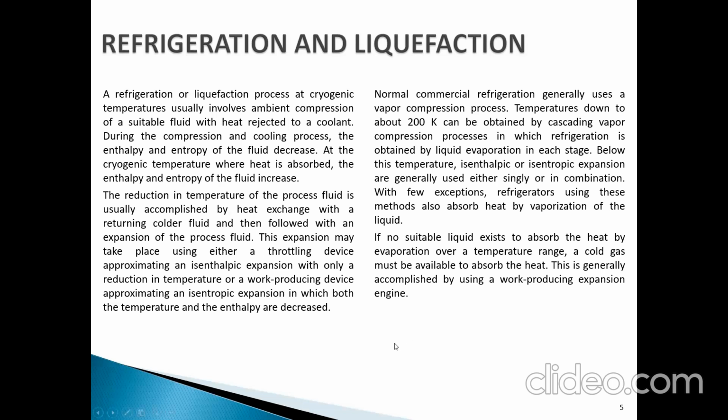If no suitable liquid exists to absorb the heat by evaporation over a temperature rise, a cold gas must be available to absorb the heat. So this is generally accomplished by using a work-producing expansion engine.